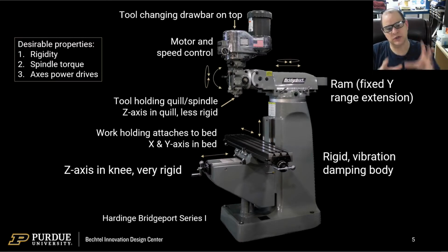But you should really only be using that for drilling, because again, when you've got a block of steel bolted to the table and you're moving it sideways under the cutter, if you can avoid using the quill, that's great, because we mentioned you wanted rigidity, right? Well, the longer you stick out the quill and the longer your tool is, the more bendable it is. It's very much the same as if you have a stick and you wave it in the air and it whips backwards and forwards. Well, if you cut the stick short and whip it, it doesn't move as much.